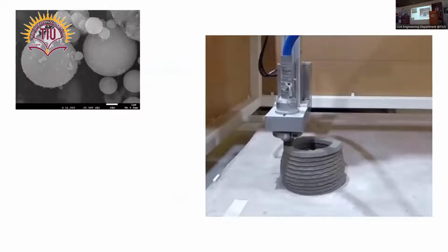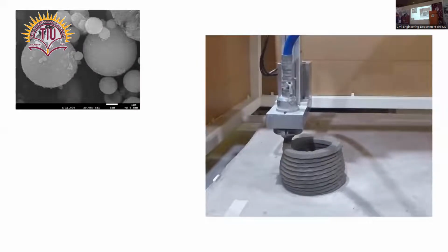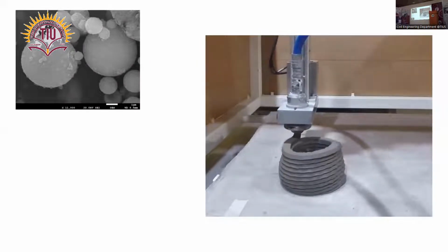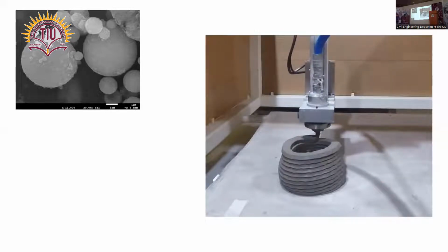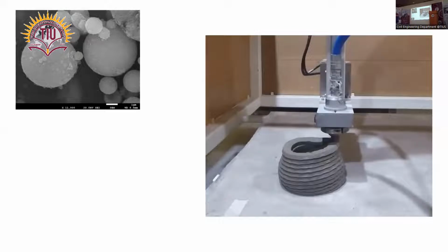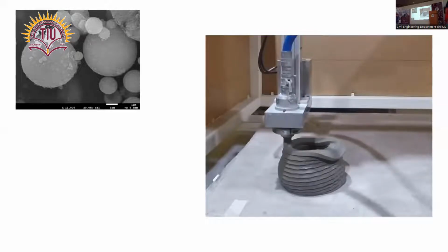But what we intended to do was replace the Portland cement with some kind of industrial waste like fly ash, slag, because we want to have some sustainable material at our end. And in that regard, we feel that when you use spherical particles in a huge volume, maybe 60% replacement, it decreases the yield stress. And ultimately, after printing a few layers, the layers are slumping, and you end up with collapsing of the layers. So this is what we observed in the beginning, that when we add a lot of industrial waste, we are not getting a stable print quality. I mean, not a stable buildability. We can't print more than 10, 20 layers.